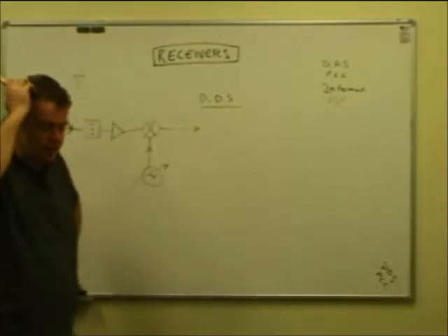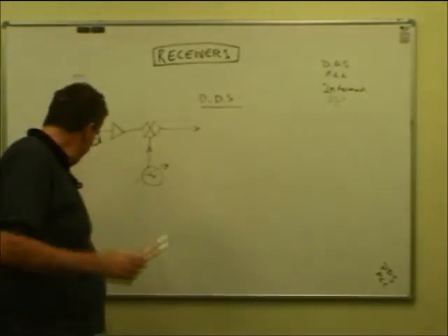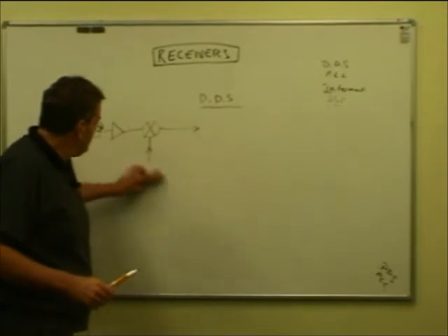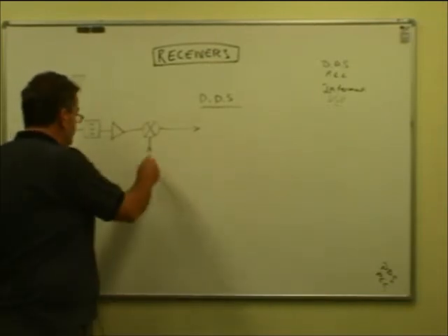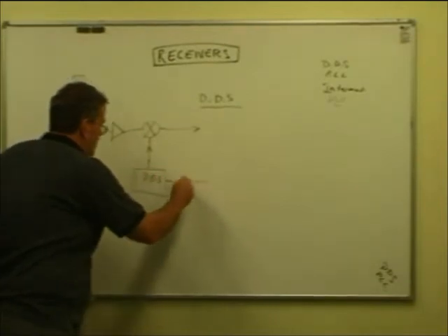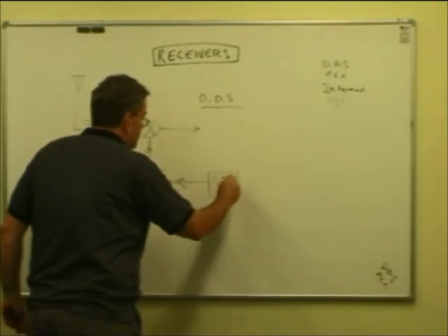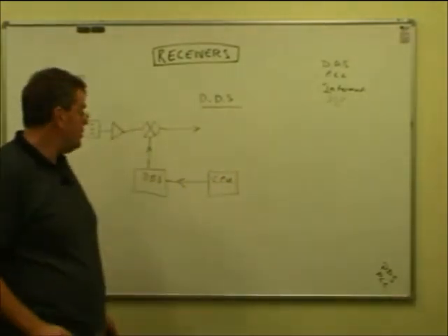And then along in the late 80s and 90s came a newer system called DDS, direct digital synthesis. And that's kind of where we're at now, a mixture of phase lock loop and direct digital synthesis techniques, such that through digital electronics and number crunching, it's replaced by a box called a DDS system. And then you've got a microprocessor, CPU, central processing unit, MPU, whatever, basically a computer.